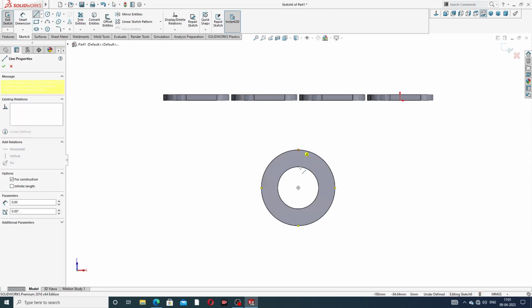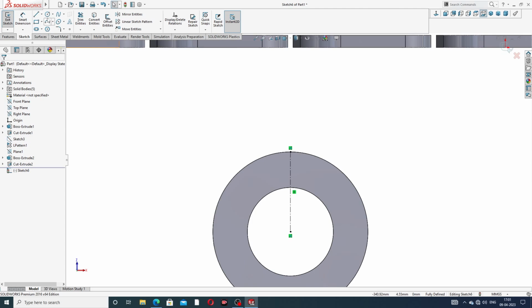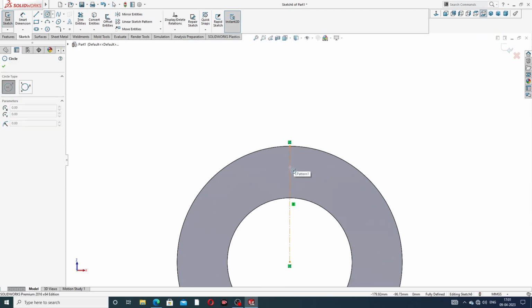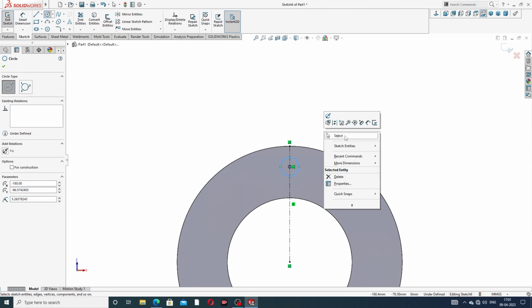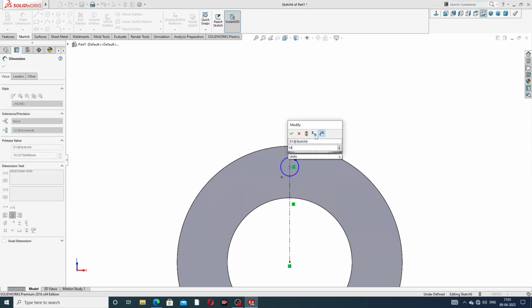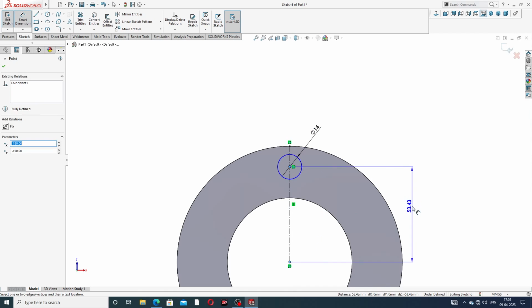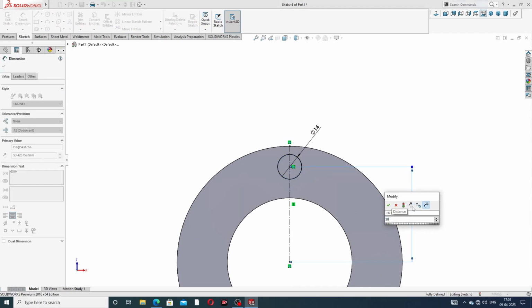And again select this, Sketch Normal, and drawing a center line, and this center line is very important because some use a pattern, and again draw a circle, and circle diameter is 14 millimeter, and this distance to this is 50 millimeter is perfect.